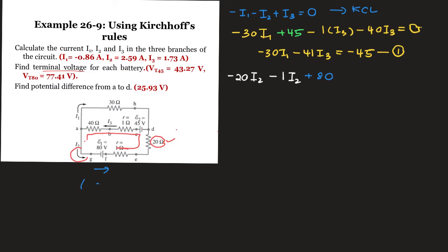Okay, done with the path of I2. Double check everything, make sure that you include all the resistors there. Then you focus on the path of I3, because like I mentioned before, this one whole circuit is going to be included in your equation number 2. So we focus on the path of I3, and focus on the second loop.